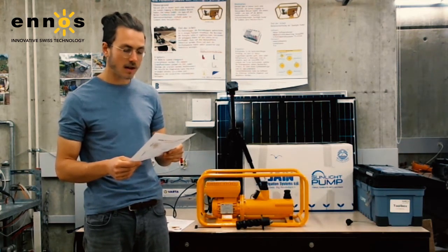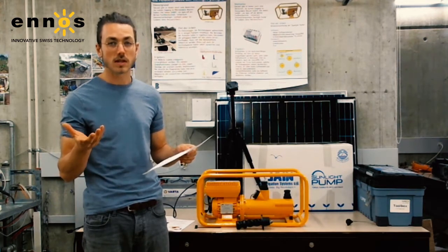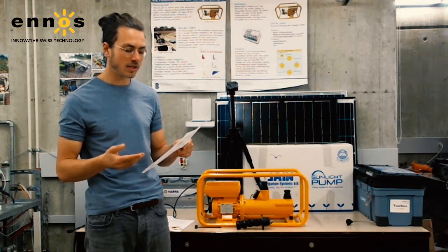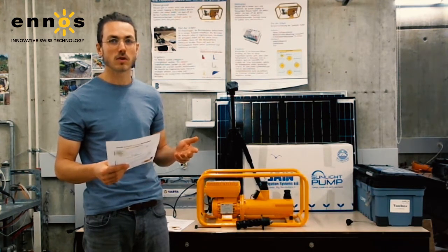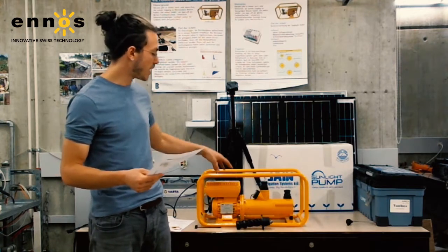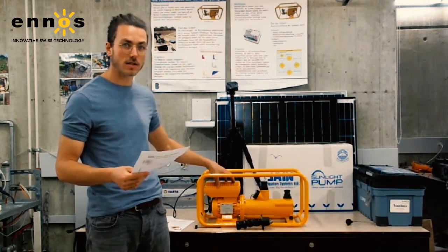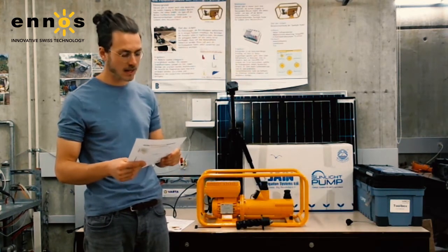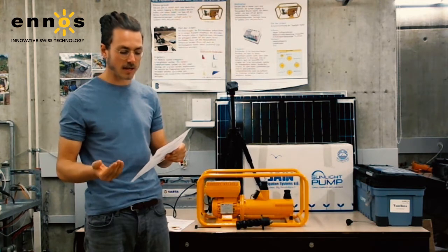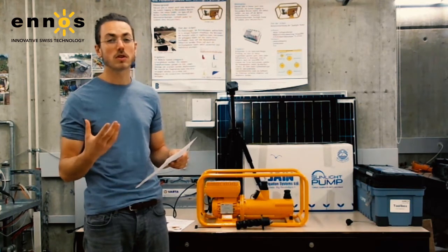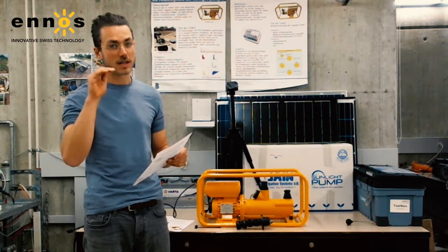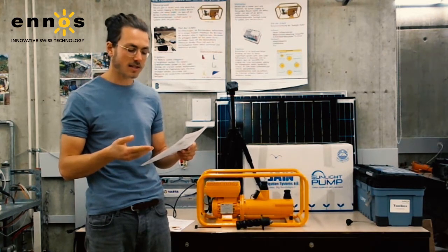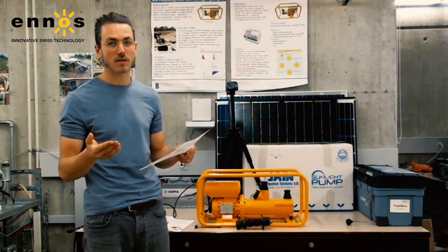Next off are 2 points which sometimes could cause a little bit of confusion. So these will be the range of maximum power point voltage. The range of maximum power point voltage is basically where your controlling electronics track the voltage of your solar panels. And the much more important aspect is the range of the open circuit voltage. And the important aspect there is the top. So this starts at 17 and goes up to 65 volts.